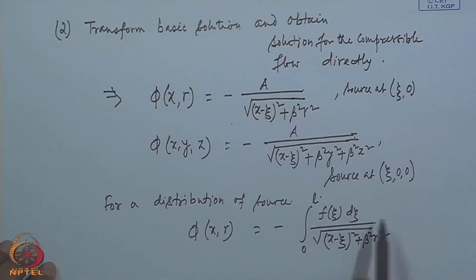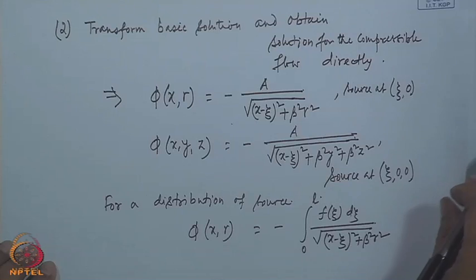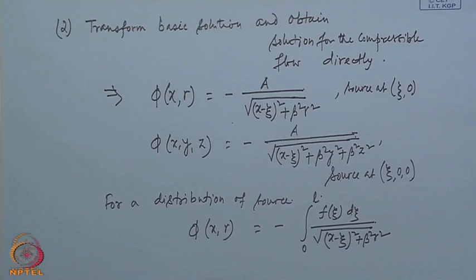this of course now has to be placed at a number of discrete points and then compute the influence coefficient matrix, that is what would be the velocity induced at all the points where we are placing the sources due to a source at a particular point, and that has to be repeated for all the points, giving rise to an n by n matrix if we have sources placed at n number of points, and the boundary conditions will be satisfied at n number of points.